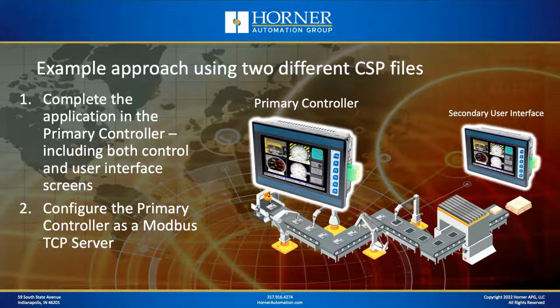We're going to go into that primary controller's program and make sure it's configured as a Modbus TCP server, okay, sometimes thought of as a slave. There's only a checkbox we have to check to accomplish that, because all the screens, all the other OCSs that are going to be accessing the primary controller, they're the ones that are going to act as masters, or as clients for better nomenclature.